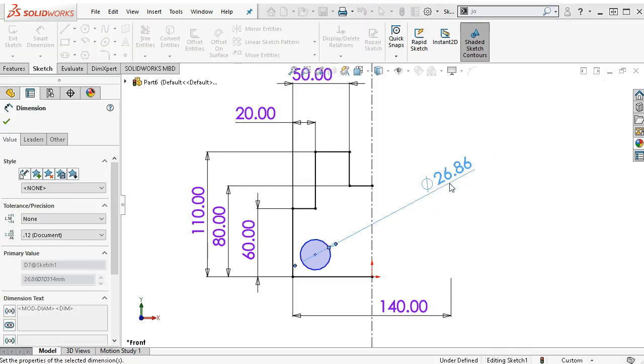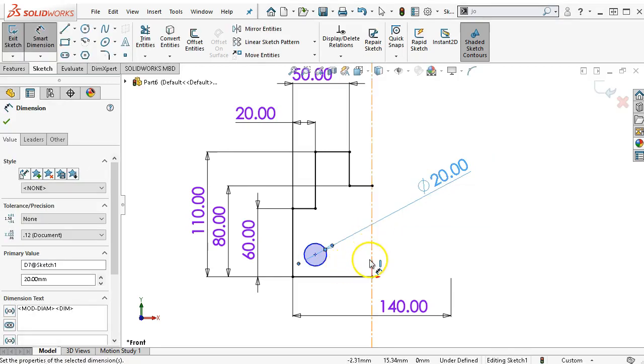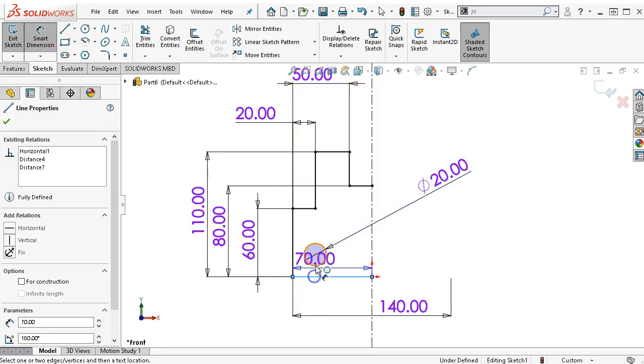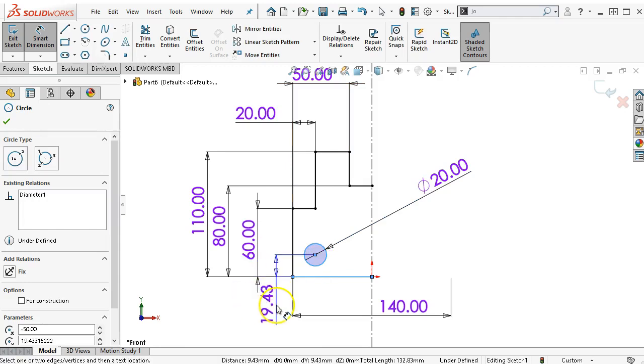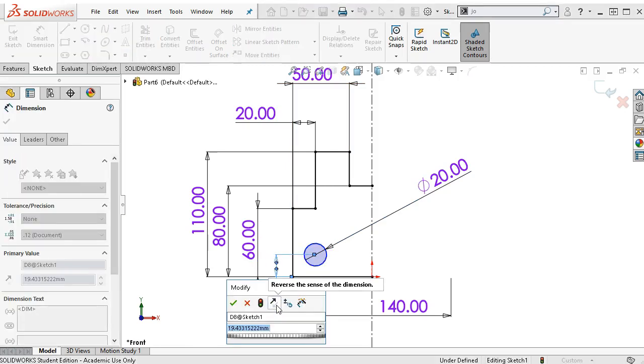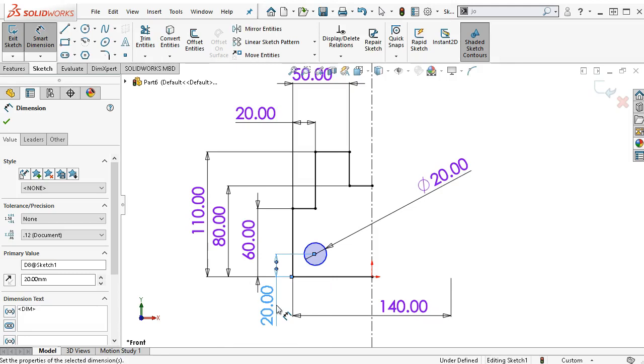Alright, so if it's at the axis of symmetry and there was a circle here, it would basically flip over and I would end up with two circles. It wouldn't cause too many problems, but it would cause a duplicate entity. So, again, not necessarily my preference to have that. So 25 off the edge or 45 from the center.